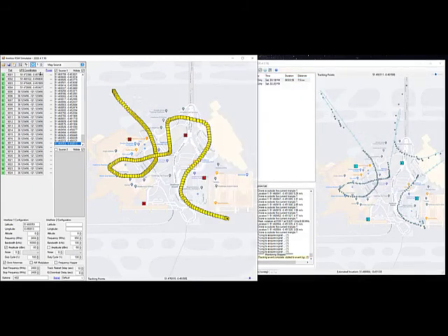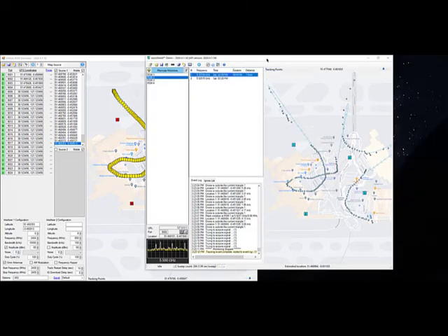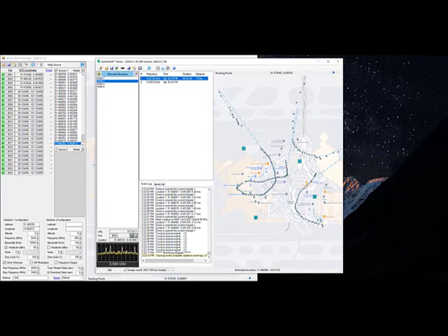To move probe positions, move your pointer to the GPS column, hold down the control key and move the wheel to go up and down, or hold down the shift key and move the wheel to go left and right. And we can update the probe positions here. Right click and then update positions, and you can see the probes in the demo program now match the changed probe positions in the simulator.